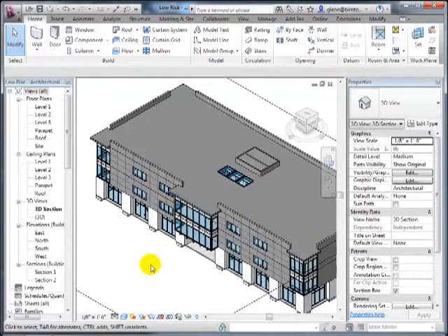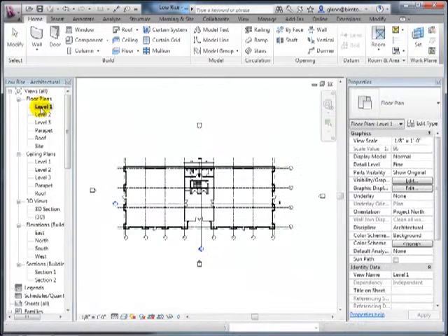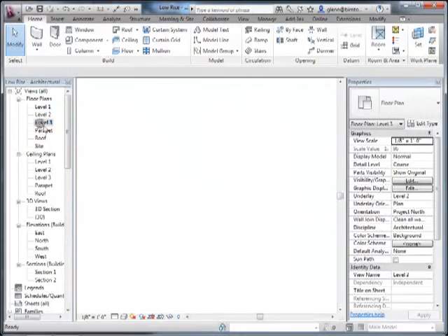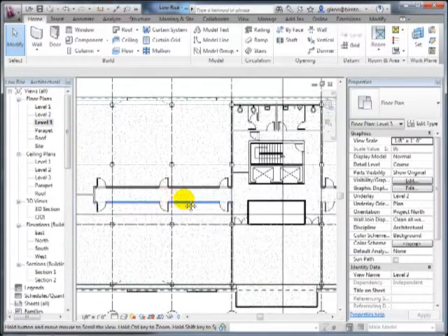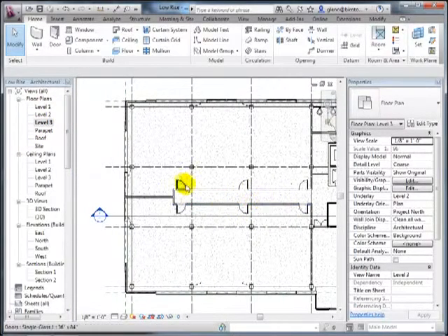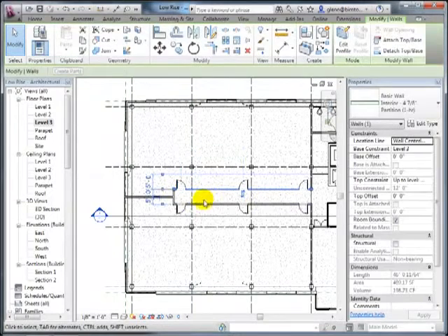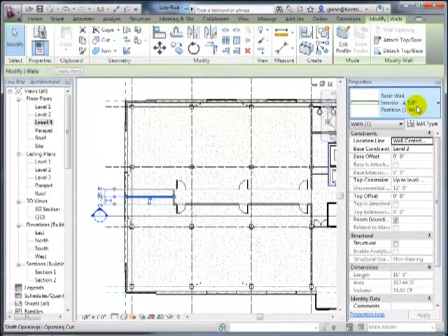And the idea with the building information model is you're looking at something that at some level looks like floor plans at different levels, and we can zoom in and take a look at any of the different elements in this model, the doors and the walls. As we go through and look at the model, any of the different elements has properties. So it's not just two lines, it's understood to actually be a wall that has dimensions to it, has a length and area, things like that.